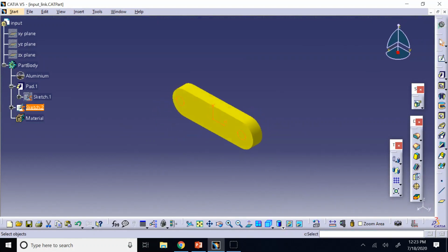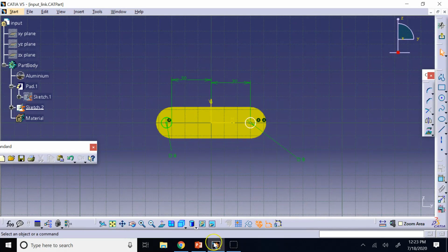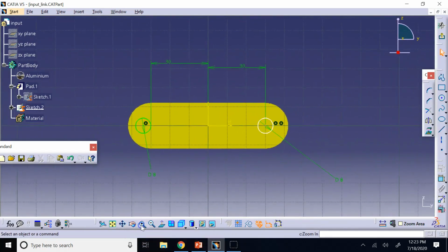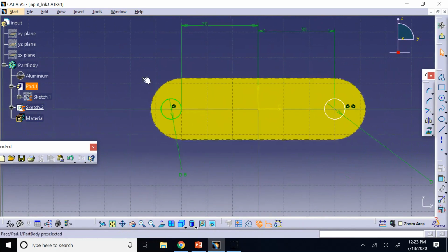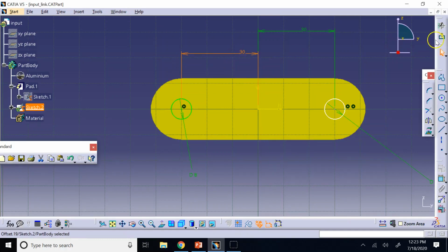And then I don't cut them. What is it? Yeah, that's the problem here. You see, this 30 is not measured from the center of the hole to the y-axis. It is measured from the right point. That is a bad dimension. Don't ever use that. Make sure you select the center to the center. Okay, so that is important.